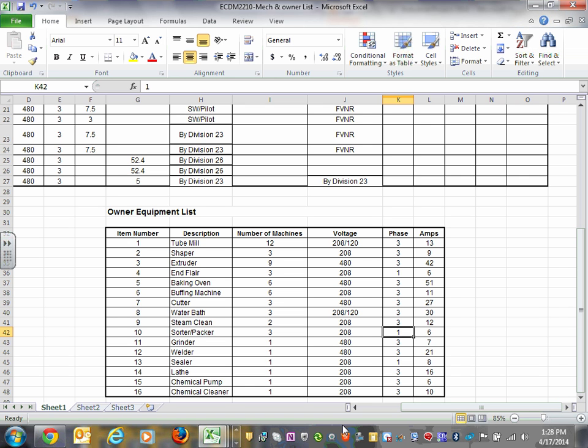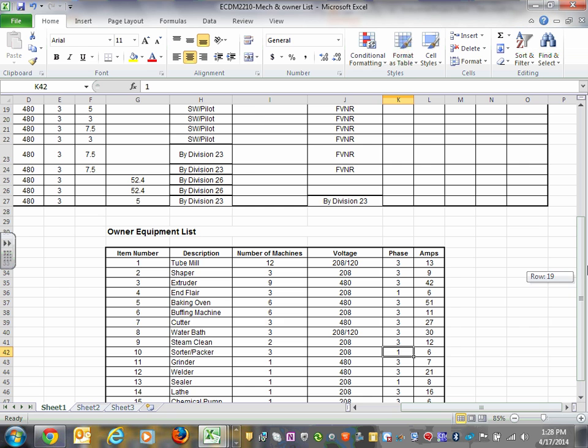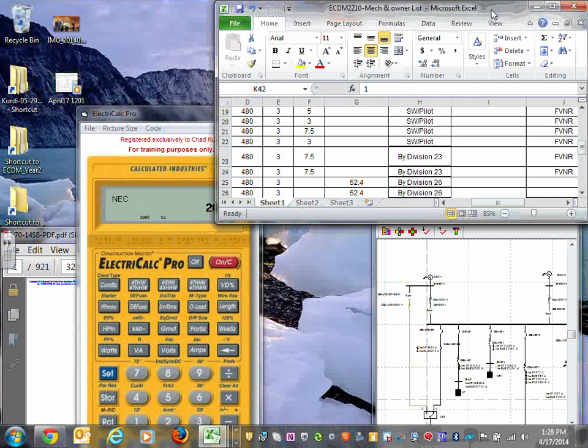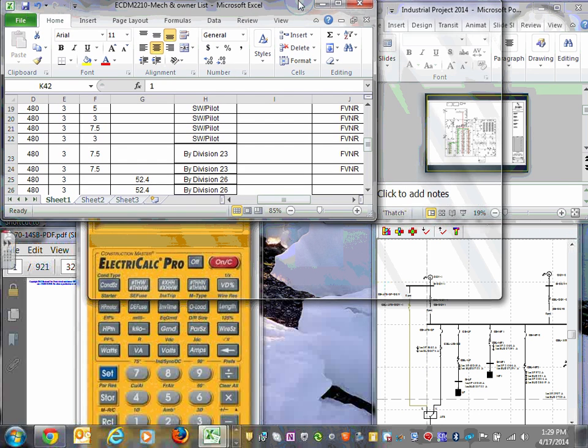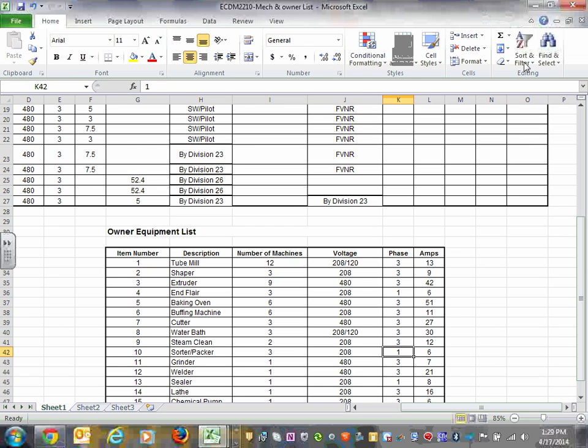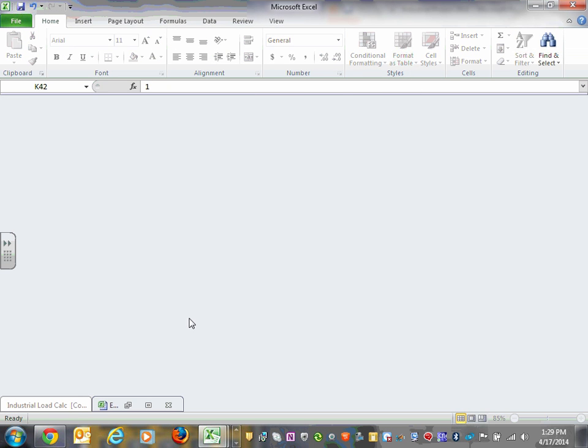Okay, so you can see that there are 2 types of loads based on 2 voltages. So when I design my bus system, I have to take this into consideration. You can't plug it in. You have to design 2 buses or whatever your solution for this problem would be. So that's the second thing that you need to get, because you can't get it from any textbook. This information, there's nothing. You have to get it from the owner of the building and the mechanical engineers. After you do that, you get all this information.